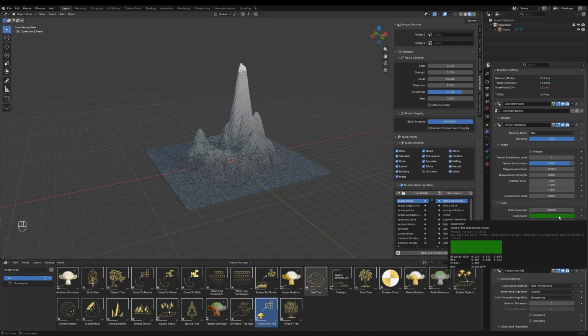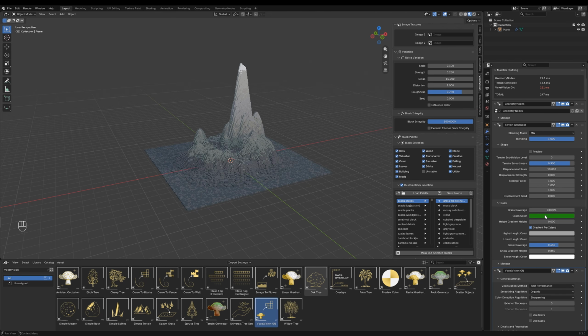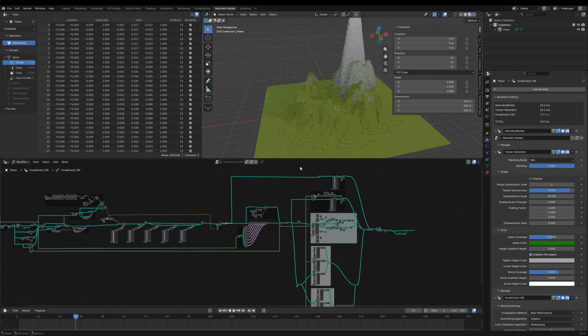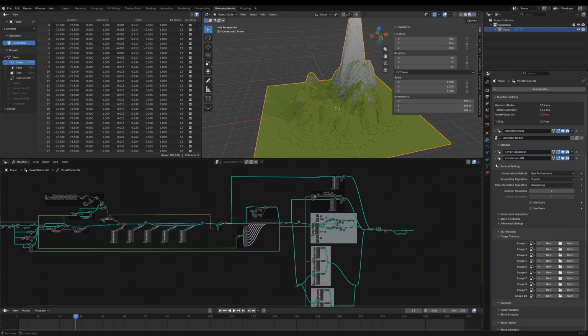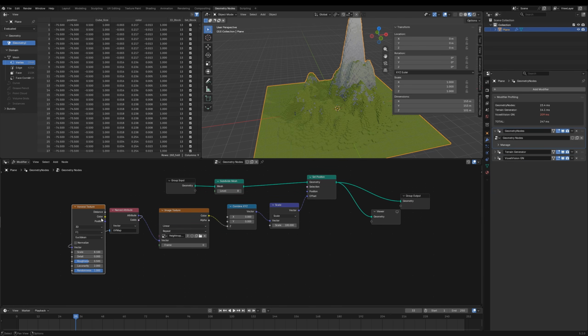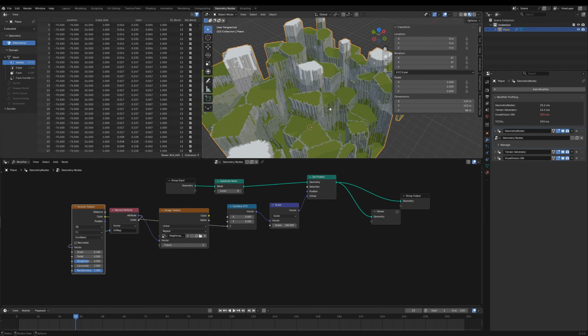So let's go and explore the other option with our custom terrain. If we go back into geometry nodes, you will see that if we select our first modifier that we just made ourselves, you can now plug this back into here, and you will see now it uses our Voronoi texture, just like this.